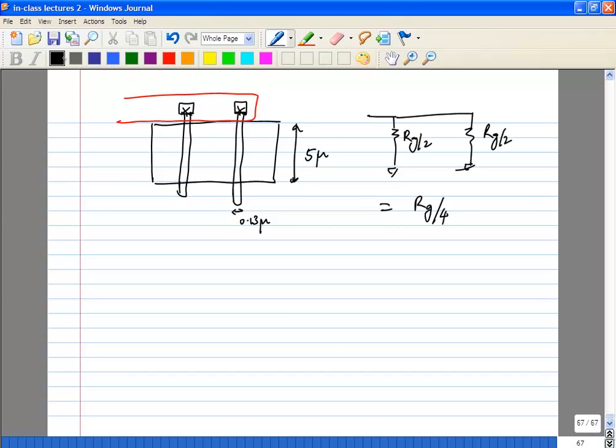You can use it. The reason I'm giving you this is because in your design, let's say you have a 200 micron transistor. Don't use a single finger which is 200 microns long. You will definitely have problems with that. In general, in an RF sense, don't try to use transistors with a finger width longer than 5 microns. So if you have a 200 micron transistor, try to have maybe 40 fingers at least.